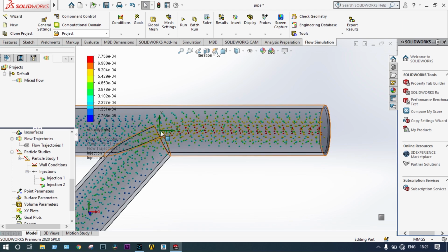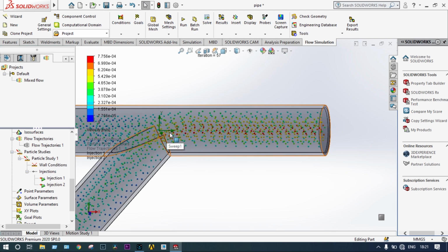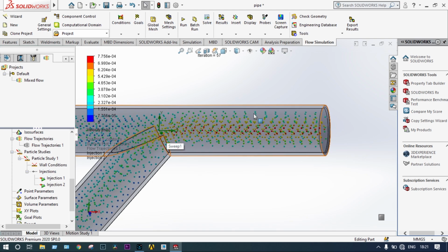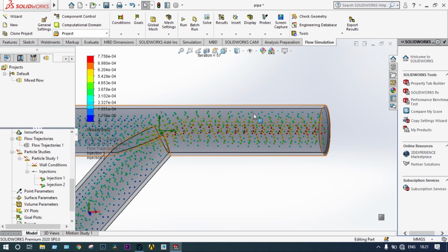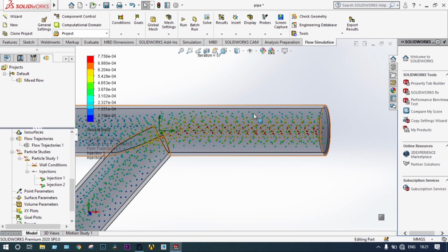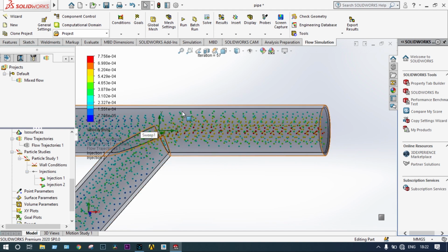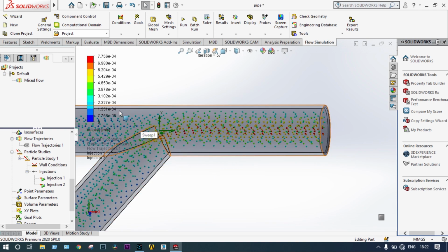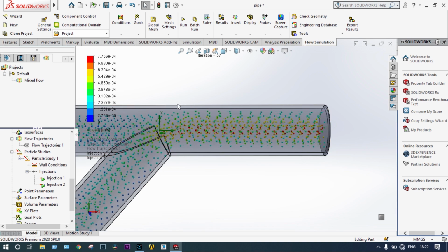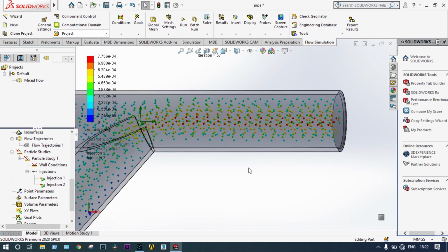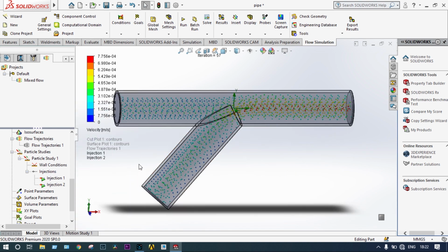After the mixing, velocity is becoming high. Even at the boundary layer, velocity is very high. Boundary layer also, velocity not 0. It should be 0, but after mixing the velocity at the boundary layer is in the level of 3.1 × 10^-4 meter per second. Right?